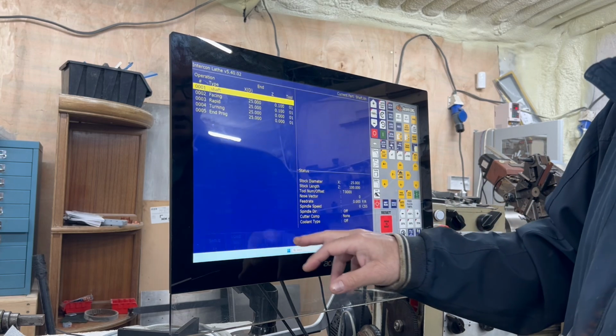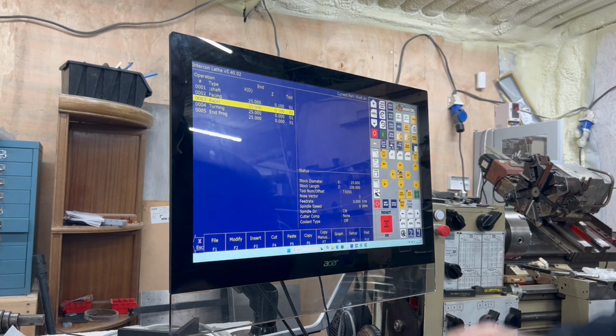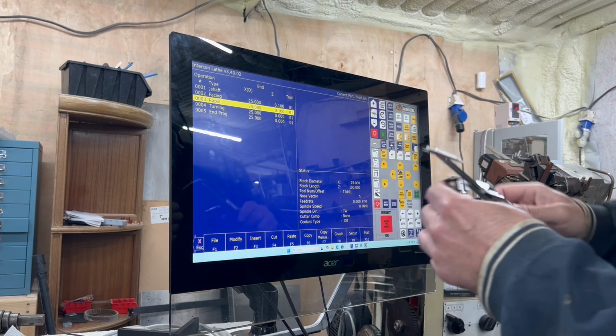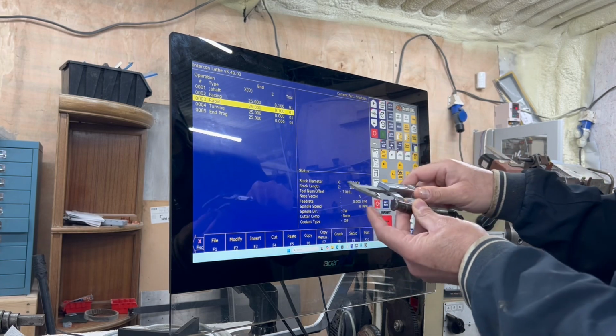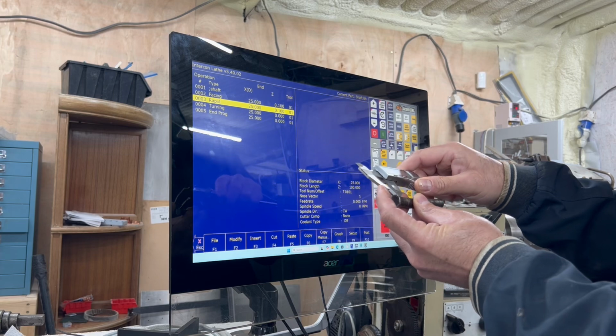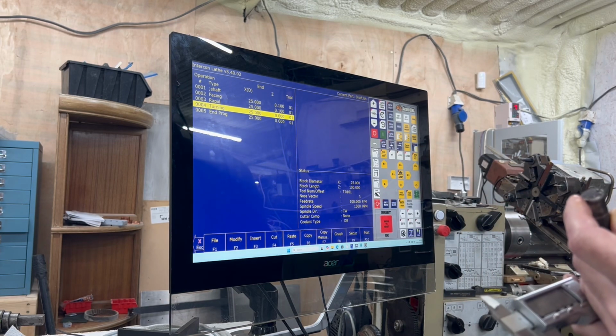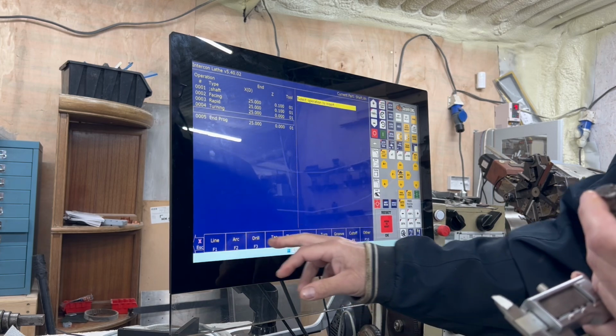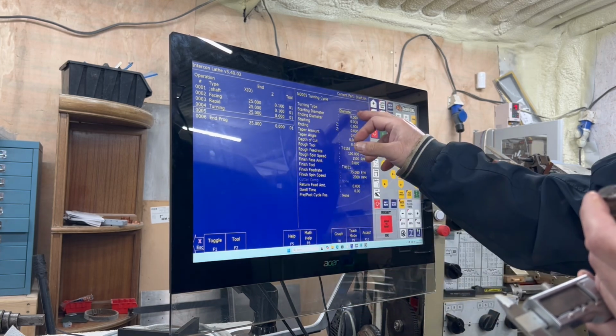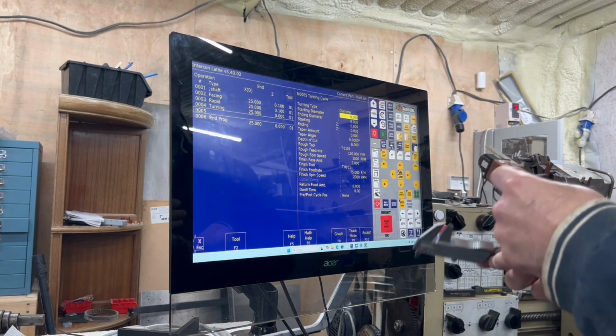What I can now do is I can do CAM. Now what we want to do is that little nip at the end, which according to this, and again this distance isn't critical, is about 4 millimeters. So we're going to do a turning operation after the last one. So we'll insert, turn, diameter turn, starting diameter.